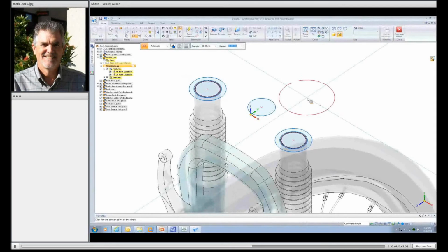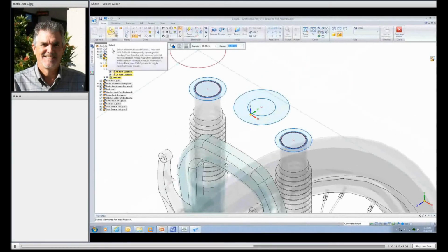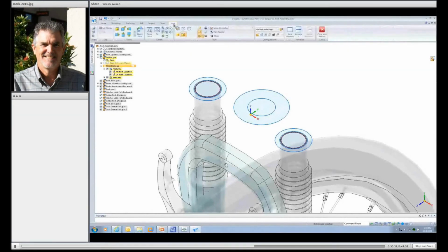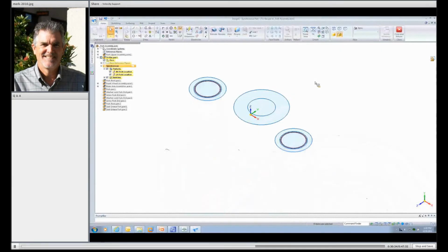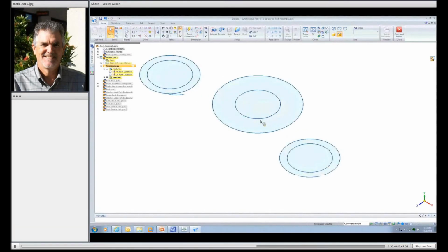And then what I want to do is finish the shape of my tri-bar by sketching some lines, and I want to make sure that they're tangent to each other. So I'm going to click and place that. You'll notice it gives you feedback as to when you're point on and tangent to your design. And I just right mouse button click to get out of the command, and then I can simply click again to place a new line. And that's basically what I'm doing. So when I see the point on and tangent, I click to place it, and then I right click to get out of that command. And then I just continue on and finish my design with the last one.